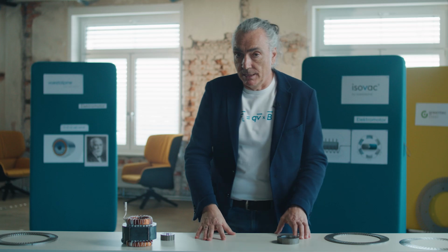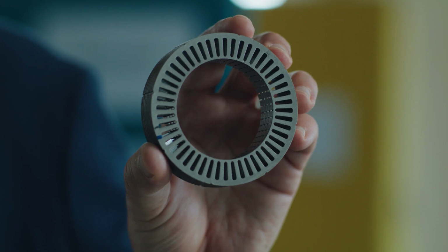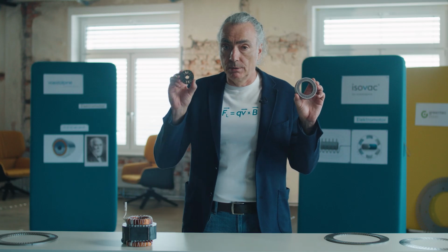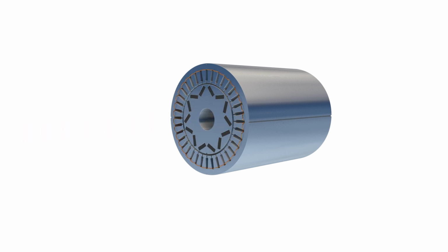Let's take a closer look at an electric motor and its individual components. In addition to various electronic components and wiring, each motor has two essential parts called the stator and the rotor. The rotor is a moving component that transfers rotational energy through the drive shaft to the application that is being powered. The stator typically surrounds the rotor. It is stationary and does not have any moving parts. The crucial question is how we get the rotor to rotate.